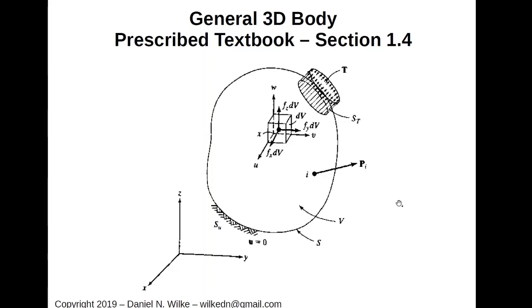Alright, so where we are now in the course is essentially we've gone from the displacement fields, we've differentiated that, been able to relate that via two material parameters using the generalized Newton law, taken the strains to stresses, and now we're sitting with a stress field, which is a function of x, y, and z. Okay, so we've got that stress tensor, or that stress vector, that 6x1 vector that we've constructed now. That is a function of x, y, and z. So it's some field.